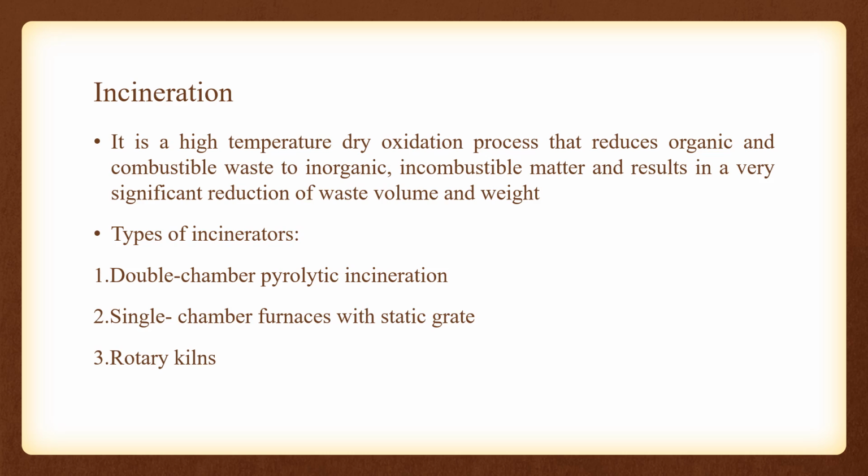The first one is incineration. What is incineration? Incineration is a high temperature dry oxidation process that reduces organic and combustible waste to inorganic incombustible matter, and results in a very significant reduction of the waste volume and weight. This process is usually used to treat waste that cannot be recycled, reused or disposed of in a landfill site. Types of incinerators: there are three different types.